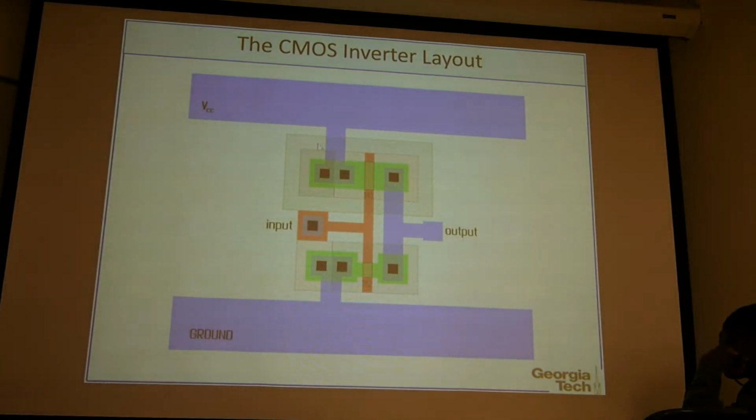You will see this kind of layout. And basically here different regions are for different, let's say, source and drain regions. So here the bottom one, this is NMOS, and this is a PMOS. So here, this is the input contact, and this red wire, this is interconnect. This is the interconnect we have talked about before. So this metal wire, this red one, is a gate of NMOS and PMOS. So here this is NMOS, and this is PMOS.